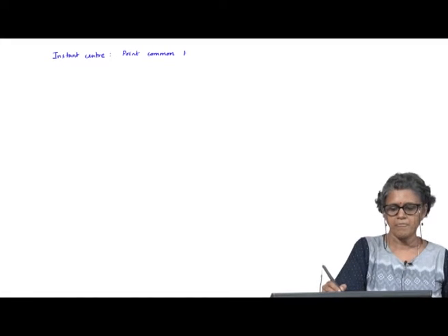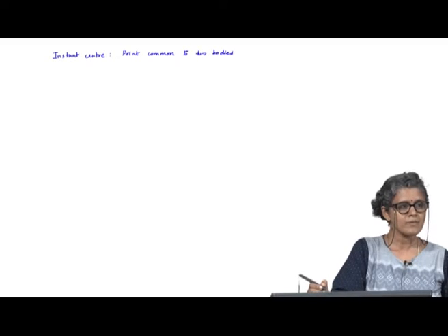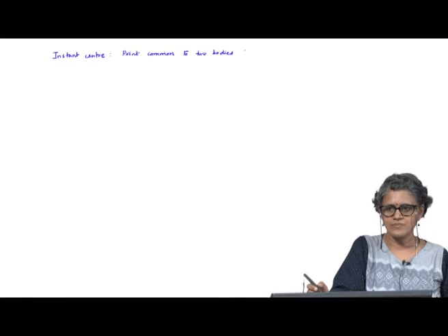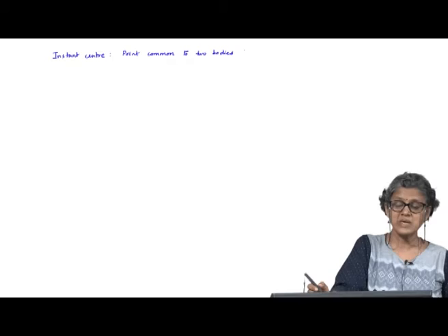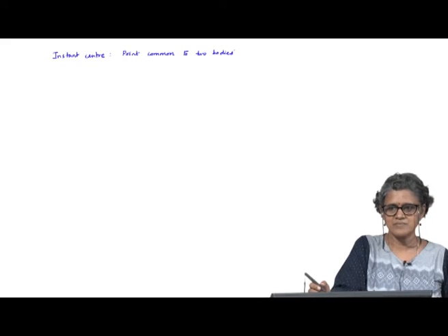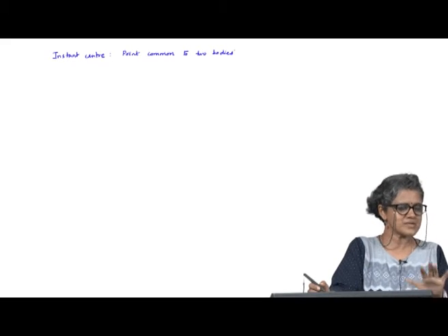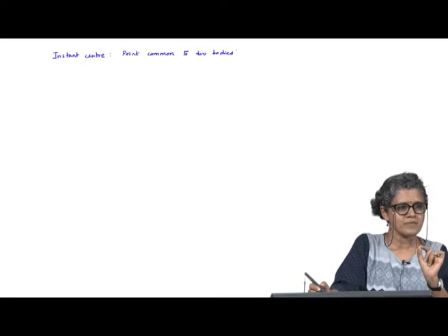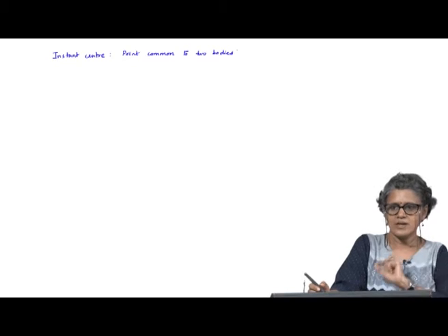Okay. What else? There could be many points common to both bodies. What is special about this point? The relative motion of one body with respect to the other is pure rotation. Okay, which means what? So, that point acts like a hinge, which means in this big scheme of things, what is the velocity of that point in both the bodies?